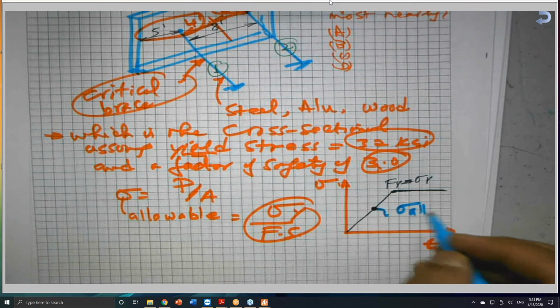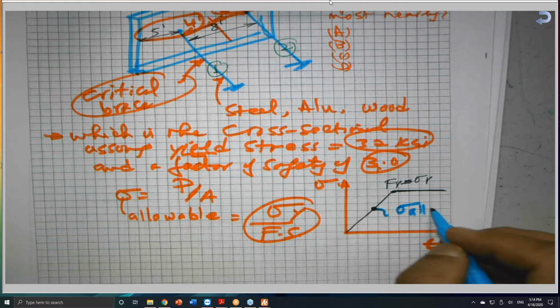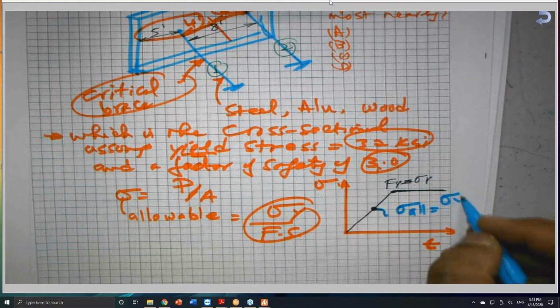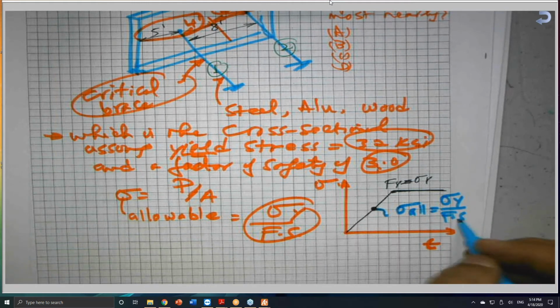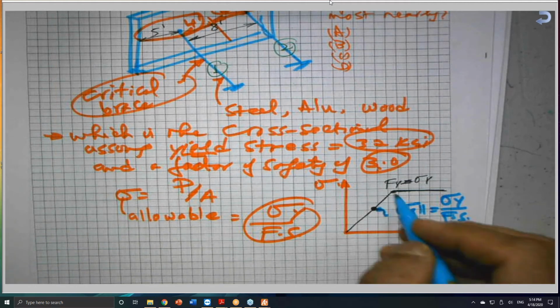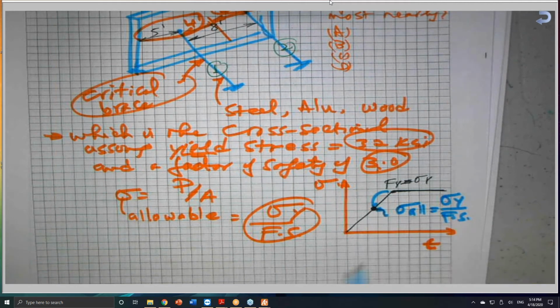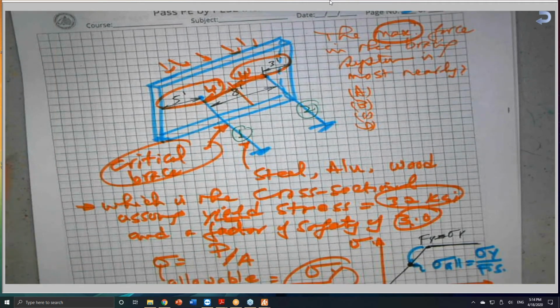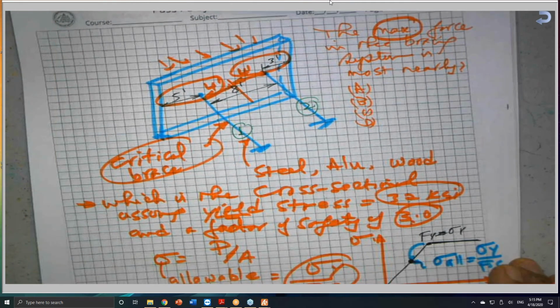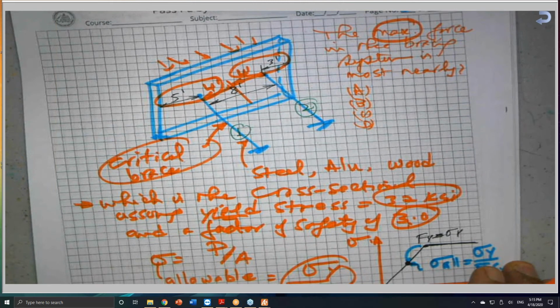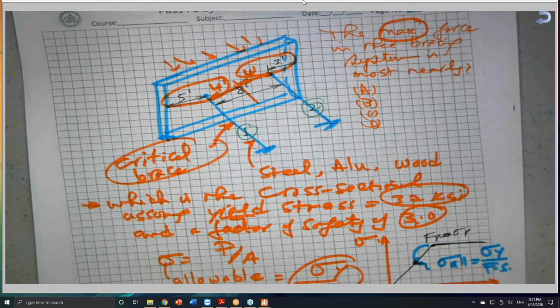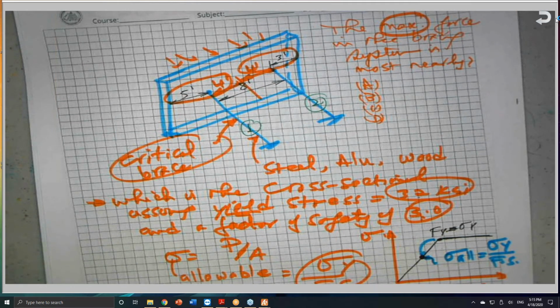Like we did for the footing design, do you remember? It is equal to sigma sub y or F sub y divided by the factor of safety. This will bring the stress from here to here, just in case the overload or the wind has been miscalculated. So I have a factor of safety, I have reserve capacity. So please look at these things. All these are variations that could be part of a problem that you see on the exam or something similar to that.